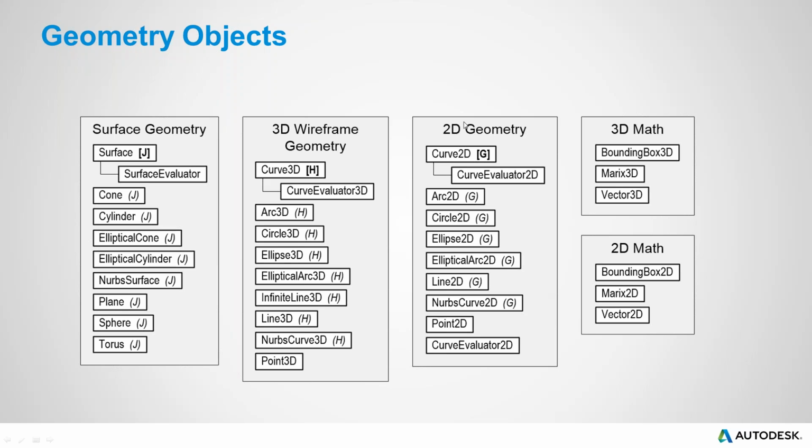2D geometry isn't used very much in Fusion because sketches are all 3D. But where 2D is used is what I talked about earlier, those CoEdges. So when I get geometry from a CoEdge, it's going to return 2D geometry, because it's defined in the space of the surface, which we'll talk about in a second. And these other ones I have up here aren't geometry, but they're just other transient objects that are used quite a bit when dealing with geometry.